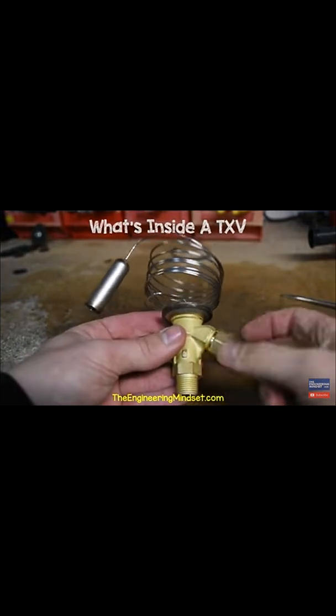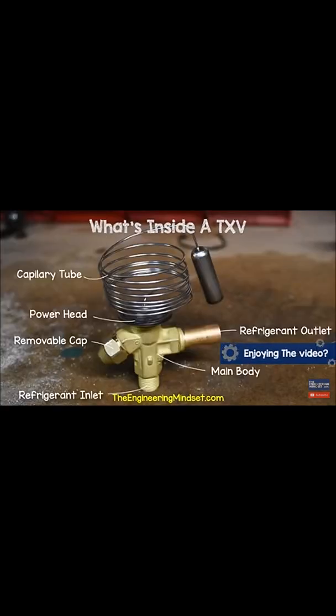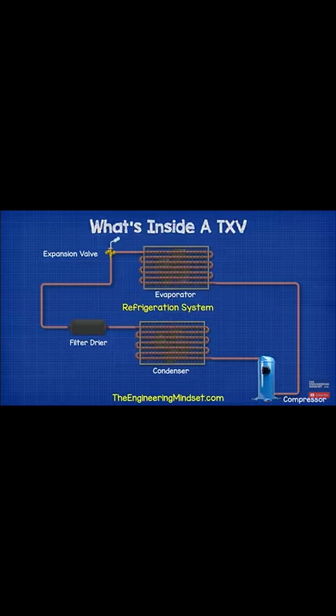On the top, we have this large head called the power head. There's also a coil of very thin tubing known as the capillary tube, and there is a large bulb at the end of it known as the sensing bulb. These are all made from stainless steel. The coil is stretched out so that the bulb sits at the exit of the evaporator to sense the superheat.